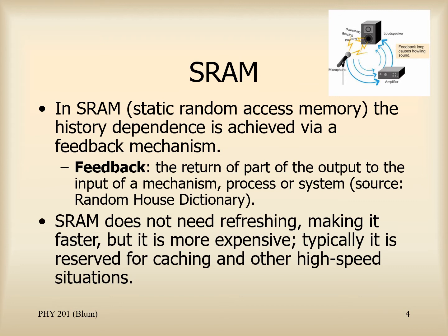In SRAM, static random access memory, the history dependence, the remembering, the holding is achieved by a feedback mechanism. Feedback is when the output or some part of the output comes back in as input. And so that is how SRAM is going to do its holding, through a feedback mechanism.